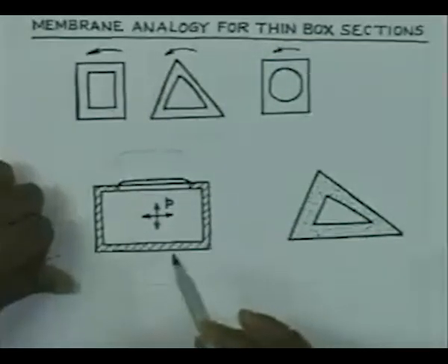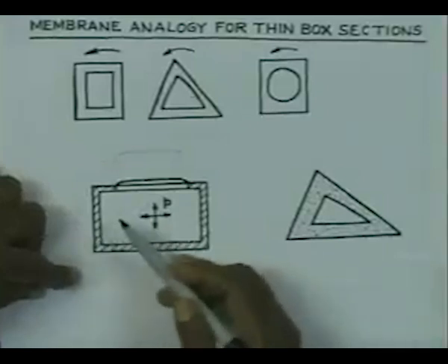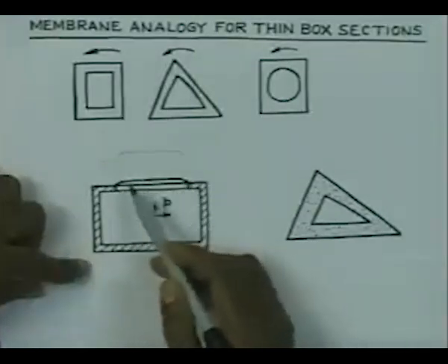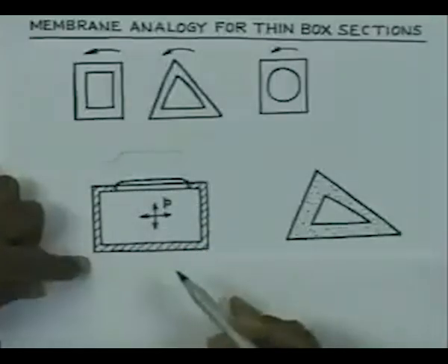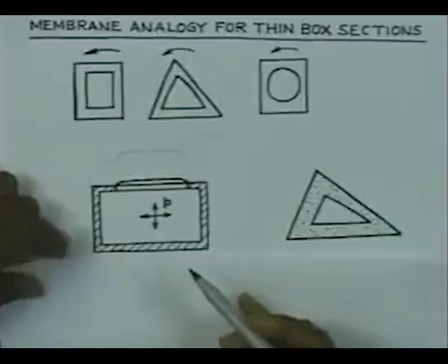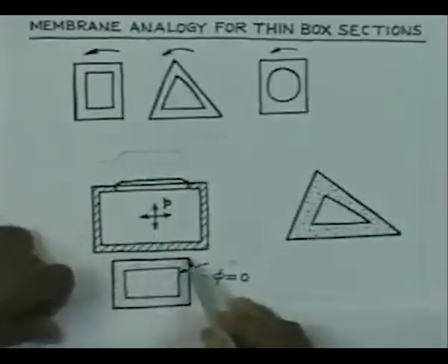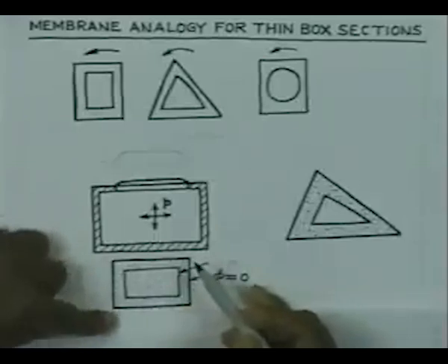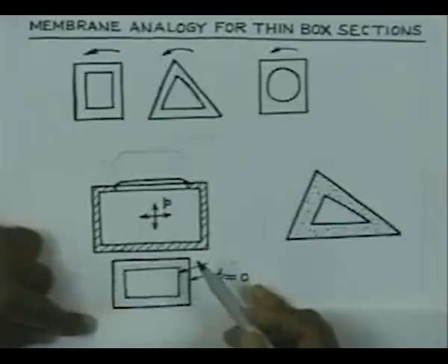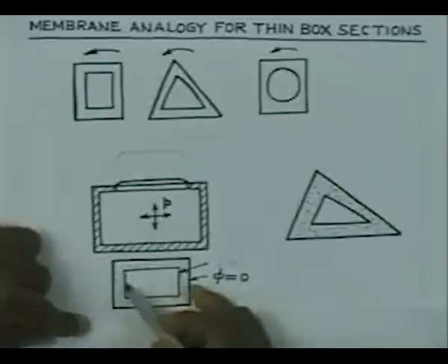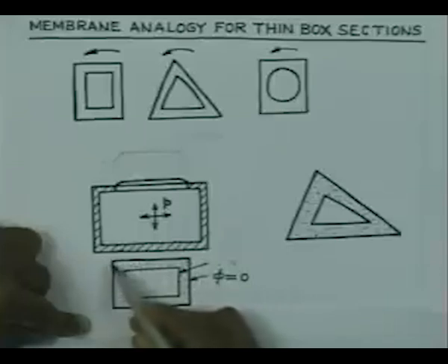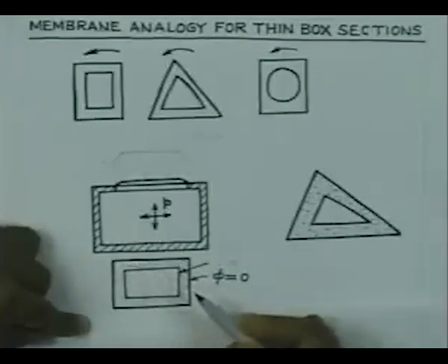then in that case the sealed box was like this, and we had an opening here. That opening should correspond to the outer boundary of the section. So, in this case our outer boundary is like this. Now, in this case, since the section is not solid, since it is hollow, we consider a metallic plate sort of placed like this. Now, a membrane is tied between the outer boundary and this metallic plate with constant uniform tension per boundary.